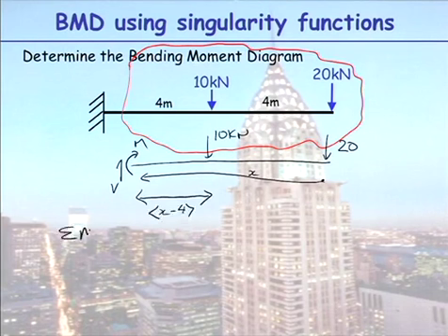Now take moments at the cut. Now can you see I've drawn the moment this way as going clockwise, because that is what a positive moment will create. But when I come to equilibrium, all the moments at the cut equal 0. All the bending moments equal 0. Let's take moments at the cut. I write that as minus M, because it is going clockwise.